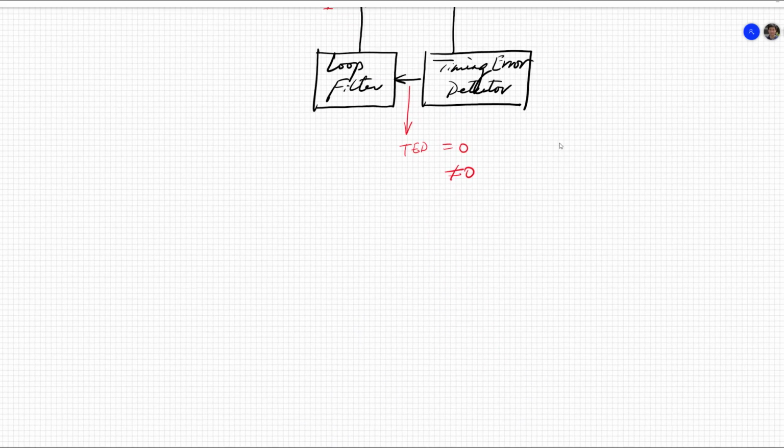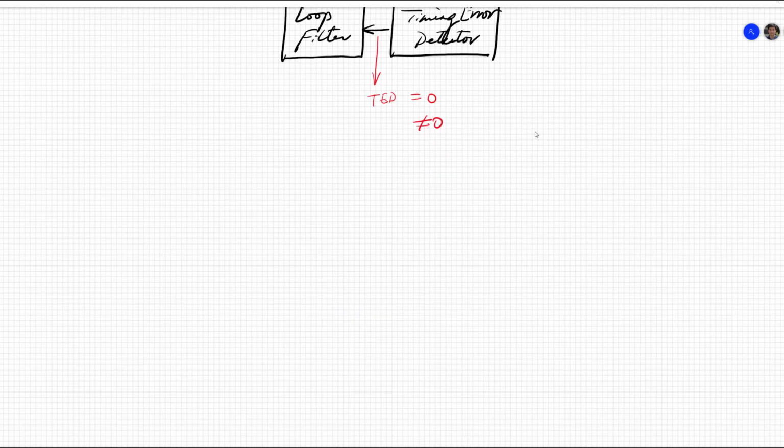So I really want to find these positions at those peaks. If I can take a derivative of my received samples, I want to find the point where dx/dt equals 0, and that will be the best position to sample.